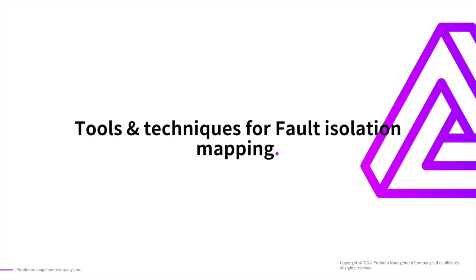Fault isolation techniques. As discussed, divide and conquer, breaking down the system into smaller sections for targeted testing. Swap testing, swap components to isolate the faulty elements, and the process of elimination, removing components sequentially to identify where the fault lies.